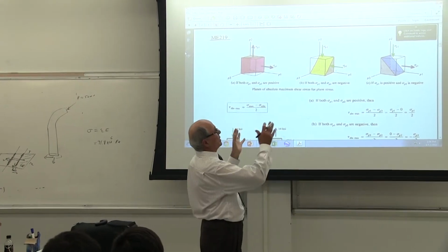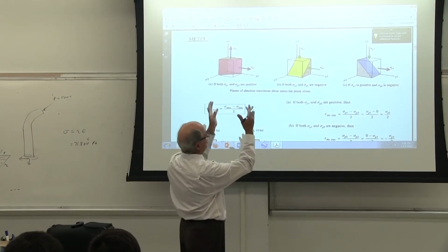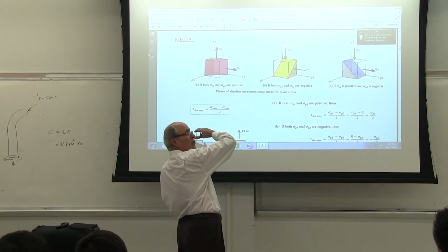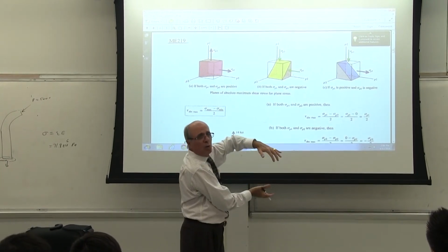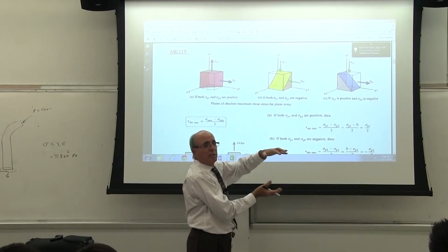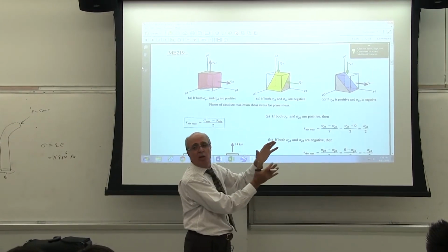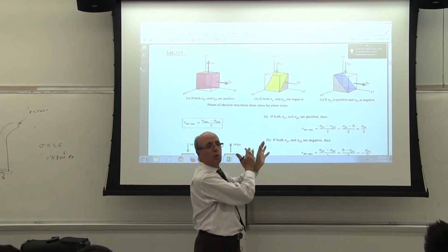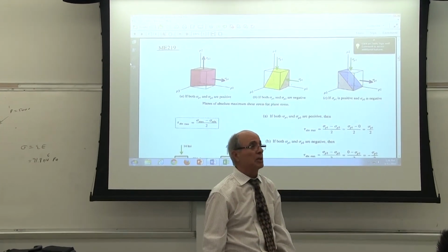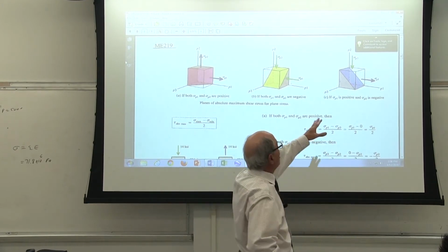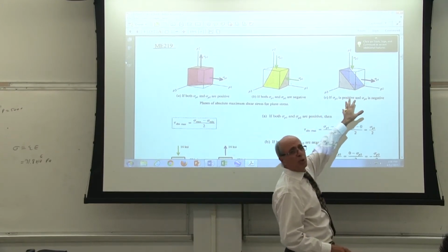Whenever you calculate, you go with the X and Y, which is usually like this. Is that correct or not? Then you go to the principal stresses, which either goes counterclockwise or clockwise. But one important thing I may not have mentioned: you are interested in the principal stress, not the original stress. Is that correct or not? Because principal stress is the maximum. Now, here they are showing the principal stresses, not the original stress.